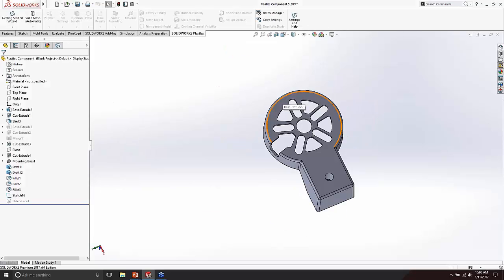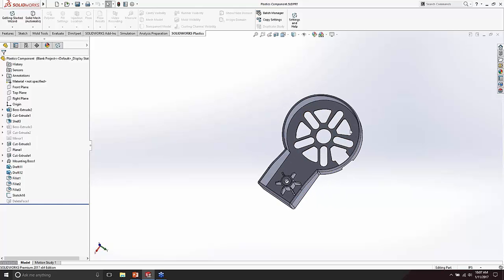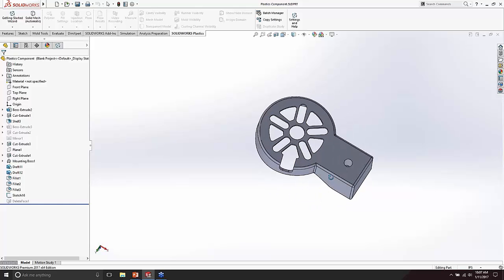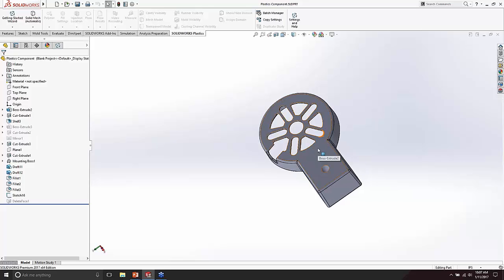So I'll go ahead and kick over to SOLIDWORKS here for us, and we can see that the part is already ready to go. Now, this is an interesting part because there's a lot of features, a lot of functions, a lot of things that are going on in here. You can see as we rotate this thing around, it is a body. There's hard-to-reach surfaces, places we might try to inject or start to push plastics in. But for today, we're going to tackle a couple of different situations where we're going to do the injections, what materials we're going to use, and overall just try and get some results out that we can analyze and figure out what the best potential solution for injecting this component is going to look like.